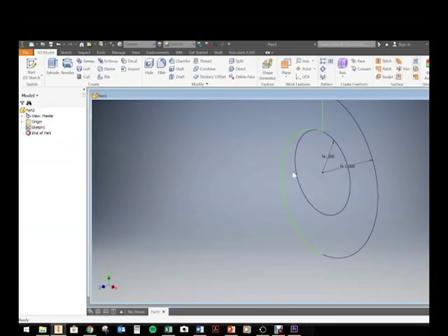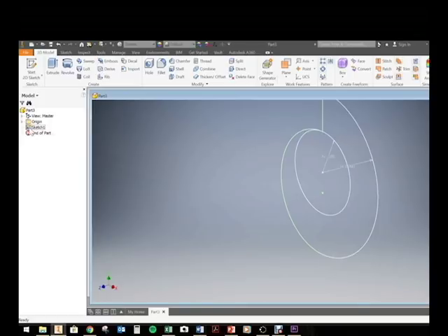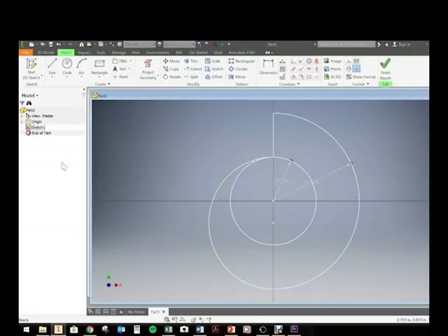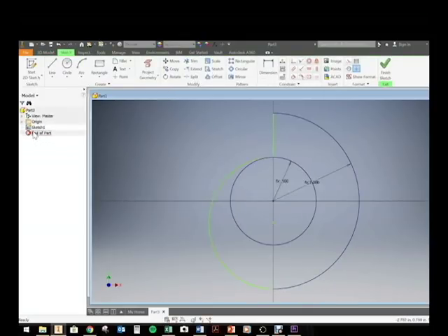If you do, by the way, make an error here, don't go starting a new sketch. That causes you all kinds of trouble. Go back to the sketch you were working on. Make sure you click on the picture portion, double click, and you can get back into the sketch you were working on. That makes it so much easier than having a new sketch there, especially when you try to extrude it later. I forgot to add my circle for the center in here.